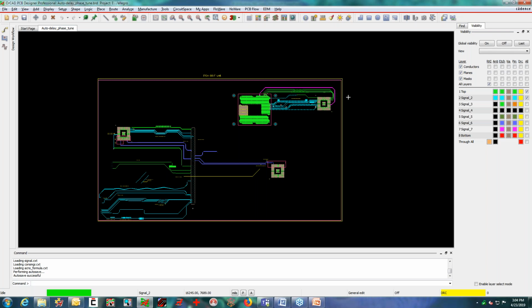I don't want to have a whole list that I'm sorting through, saying, okay, this one's real, this one's not. Because if I have to start sorting through that list, I'm in danger of missing something that's a showstopper. So if I can eliminate the ones I know aren't a problem and put them in a waived report, then when I'm looking at my DRC report, all I'm looking at are real DRCs.